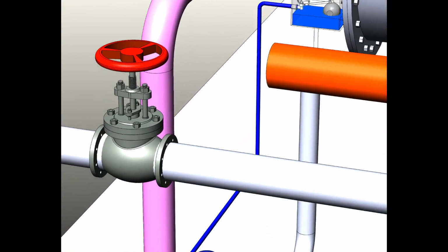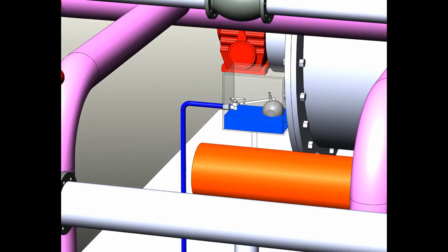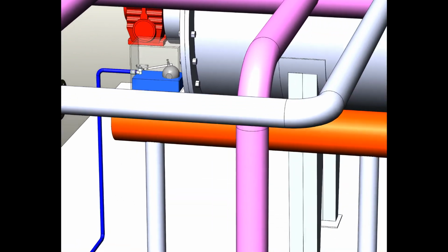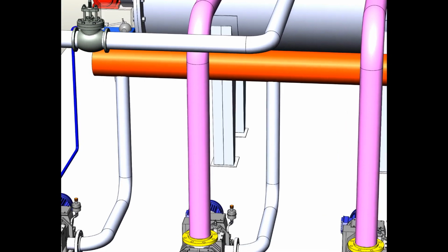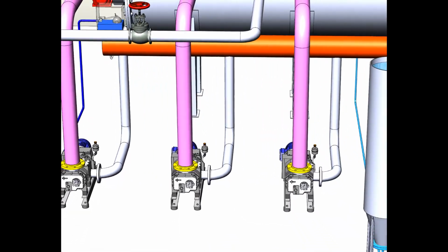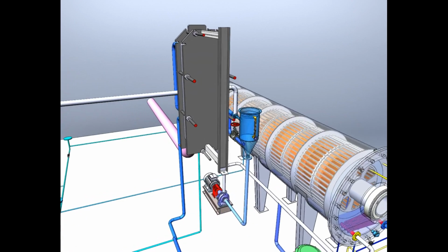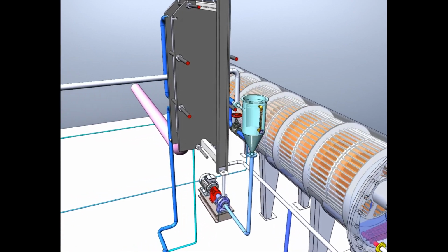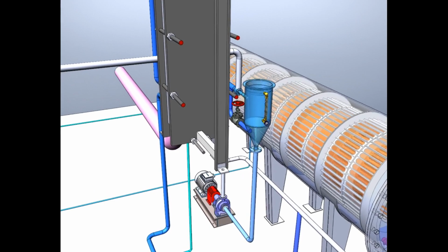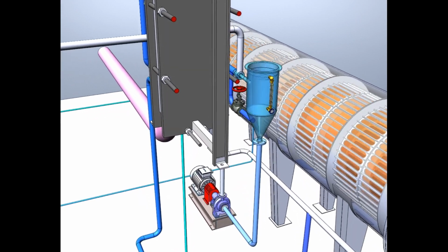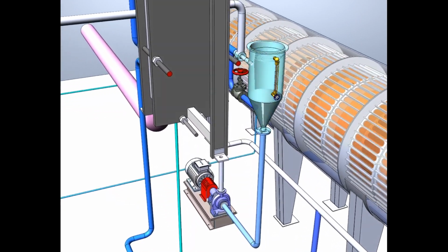The deuterium-reduced condensate can either be fed into the mass exchanger through a float valve to improve separation efficiency, or collected in light water collection tanks. The steam generation and condensation cycle provides a water circuit with a temperature of 23 to 27 degrees Celsius at a coolant flow rate of 2 kilograms per second.